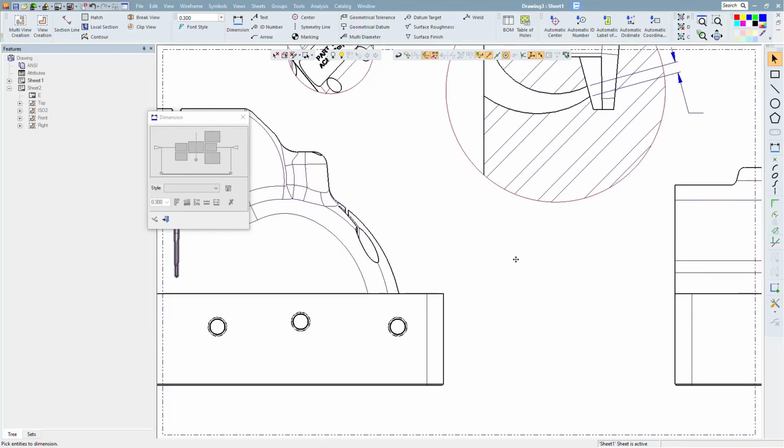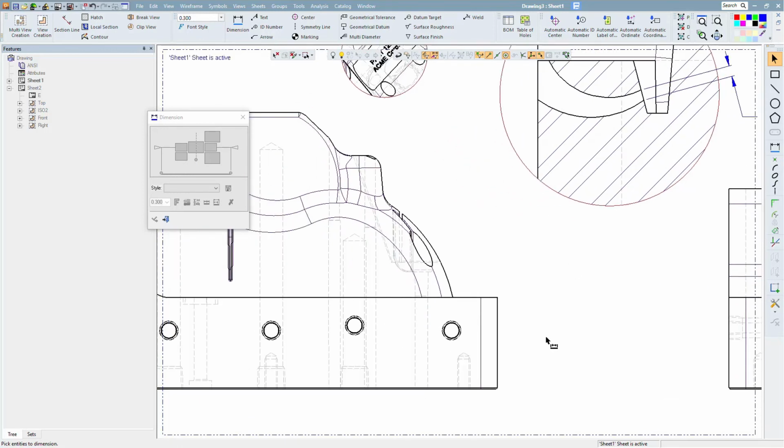And then there's ordinate dimensioning, which is a really great way to communicate information. But we get a lot of questions on it because the clicks to make them are not always so obvious. So how you do it is first click on the 0 origin point for the string. Then you select on the screen up or down or side to side, depending on the direction of ordinates you want.